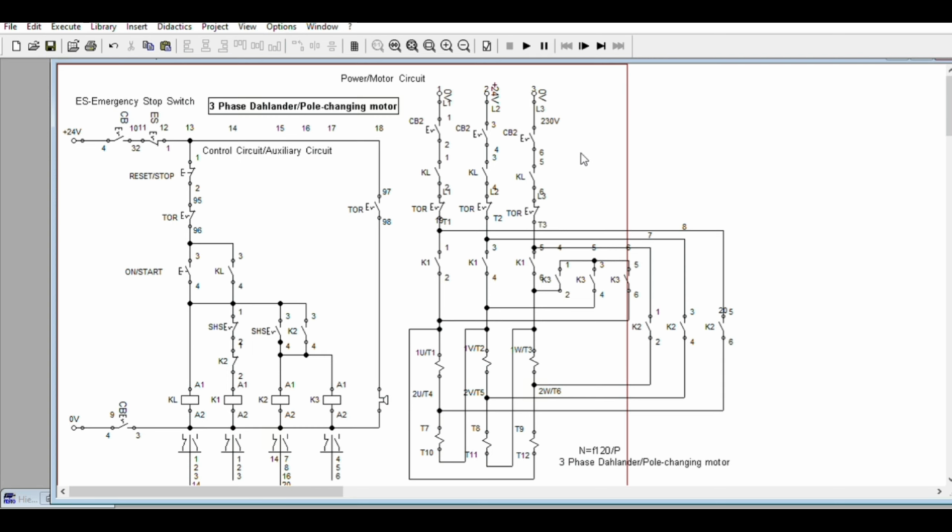That is the importance now of this line contactor, or the isolating contactor. All the currents will flow here. During the low speed operation, current will be here. When you transition from low to high, the current will still be sensed by the overload relay.